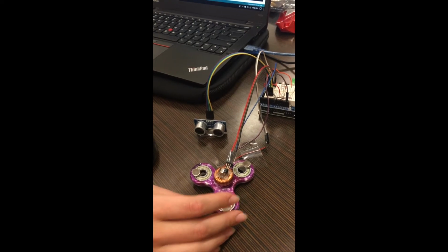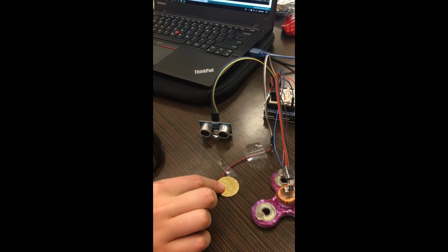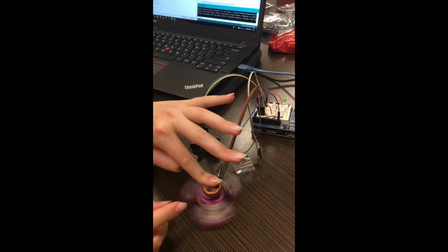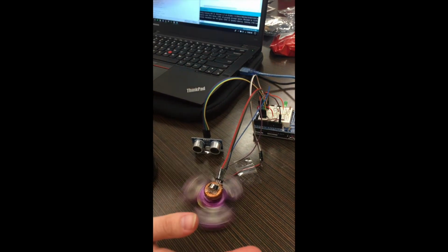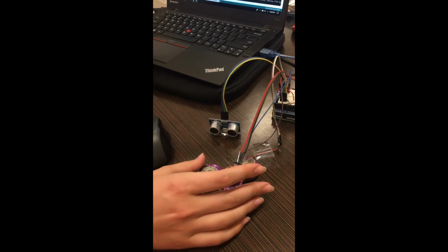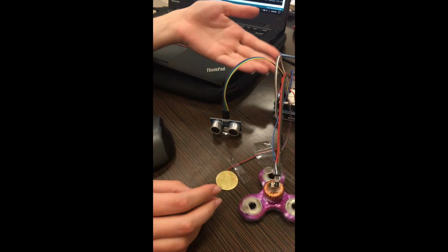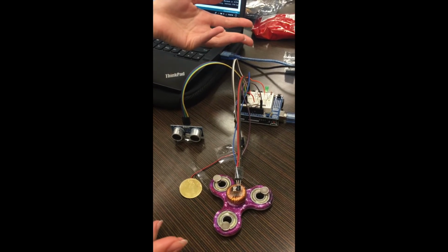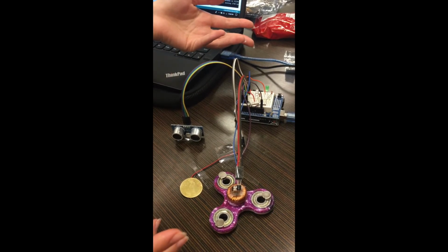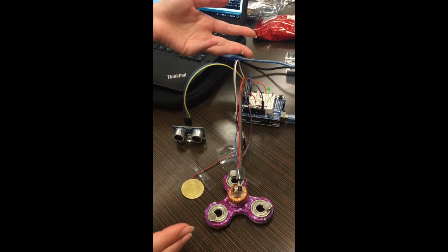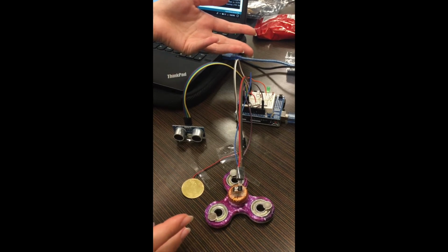The piezo disc sensor alerts the user if their device is spinning at a rapid rate, in which power is successfully being generated. As the user spins the fidget spinner, the green LED will turn on, demonstrating that a satisfactory RPM is being reached. Otherwise, the LED will remain off, alerting the user that they are not generating enough power to charge their smart device. A specific threshold for changing the high or low voltage to the LED has been set, which is based on the weight and movement feedback of the fidget spinner on the piezo disc sensor.